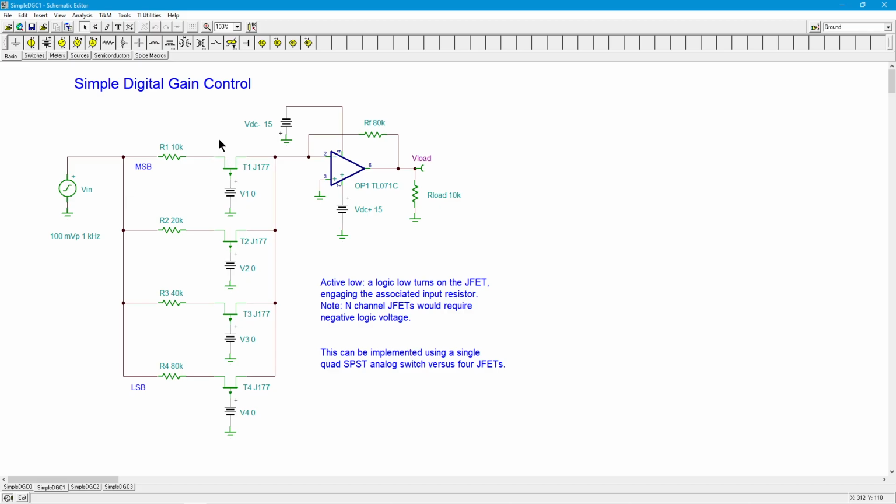But ideally you want a real switch, and the closest thing you're going to get to that is an analog switch IC. You can get analog switches where the on resistance is only a few ohms, all right? So that's going to work much better. Because, like I said, this on resistance for your general purpose FET might be 100 ohms, you realize that to get any kind of accuracy, you're going to need associated input resistors that are a couple of orders of magnitude larger than that, which is why I've got a 10K over here, okay? So, yeah, that would be a little bit nicer. But like I said, this is just sort of an introductory thing. You can breadboard this and just see exactly how it works, all right?